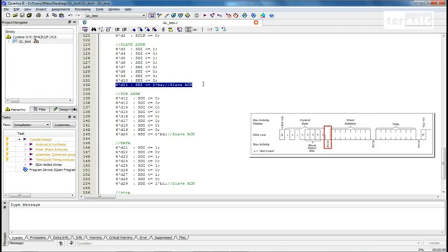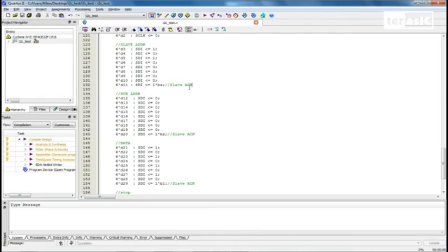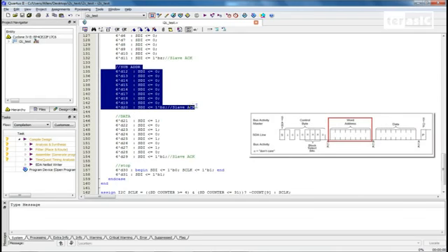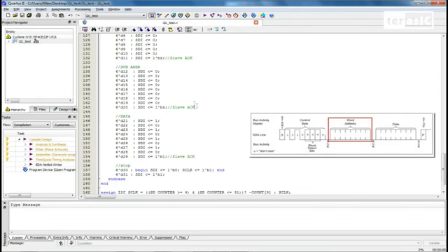If there is no pulling low and what we get is a high signal, then we know that we haven't effectively communicated with our slave device. So after there's an acknowledge there, we can move on to our sub address, which is our register address, and we'll specify as 00000000. Again, we'll wait for the slave to acknowledge by setting our bus to tri-state.